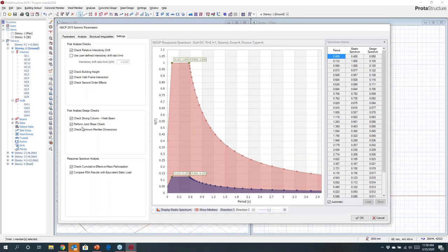We will adjust the widths of columns to suit the joint shear requirements. We will also look at whether the joint is confined or unconfined, and what I mean by that is if you have 4 beams framing into a joint, that will be considered to be confined, typically. Or if you had less than 4 beams, then it will be unconfined, and the associated checks will be different. So all these types of things we will check for you as part of the process.